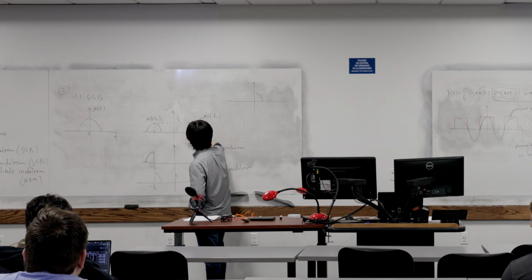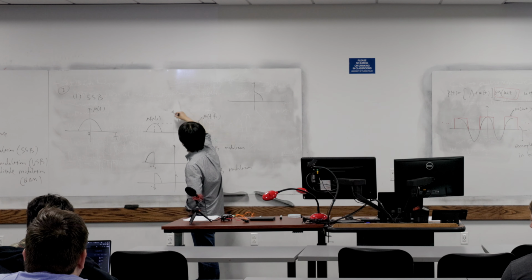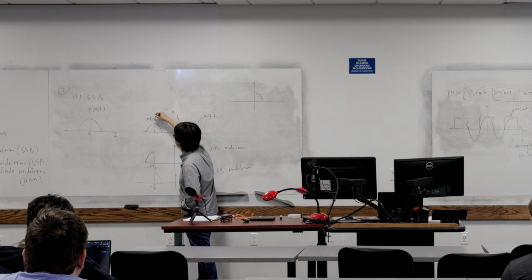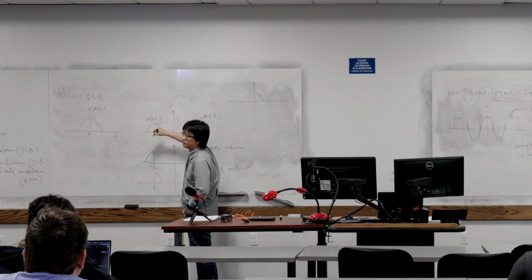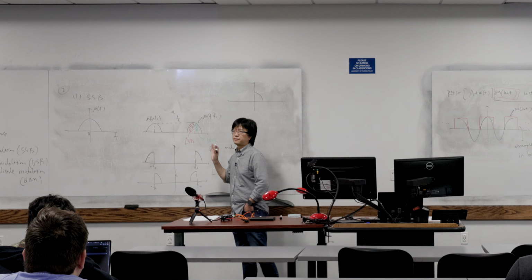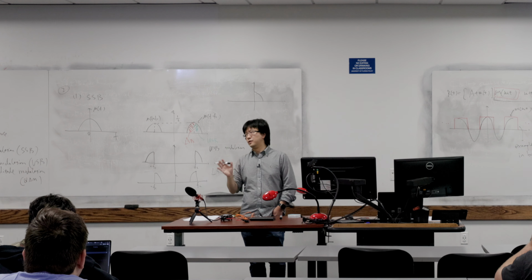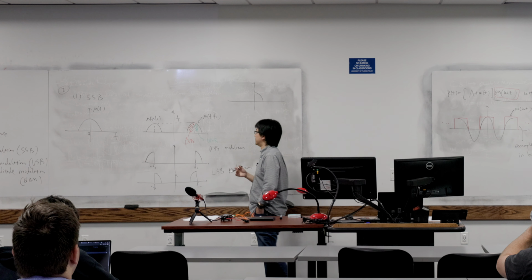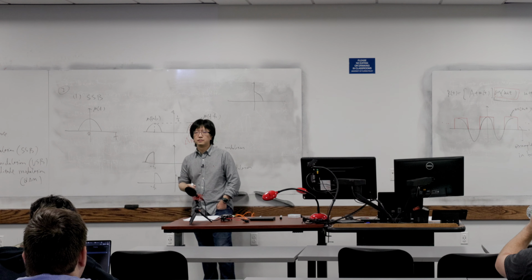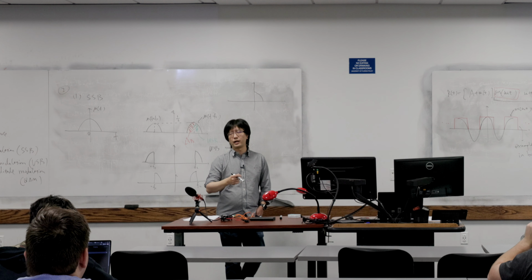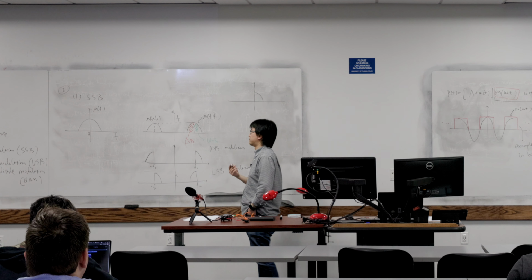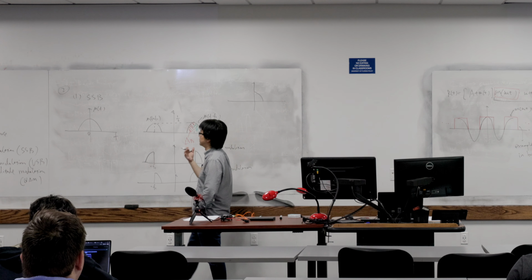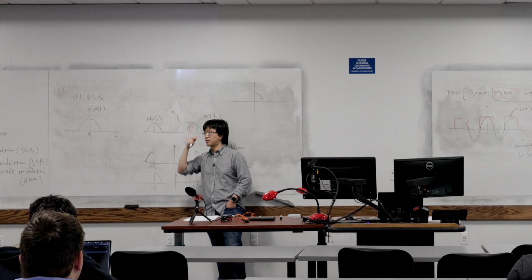Yeah, we kind of pass it through a filter to cut this half out, maybe this kind of filter, or a band pass filter. Yeah, possibly. But a band pass filter, you know, may not be extremely easy to implement. In practice, when we implement a band pass filter, maybe it's a concatenation of low pass and high pass, something like that.